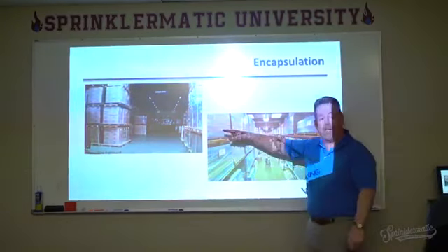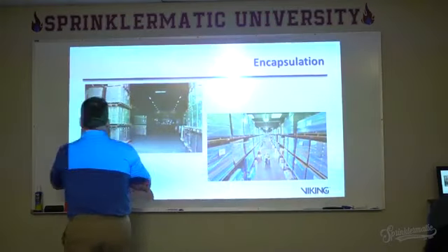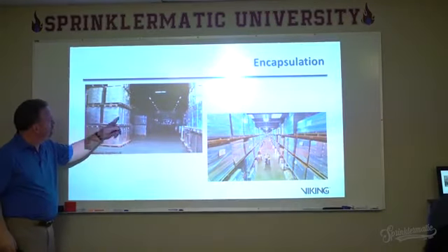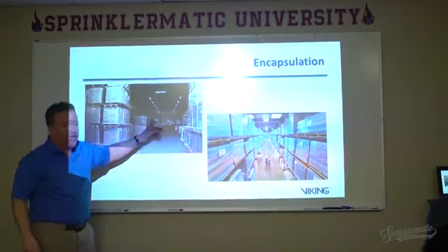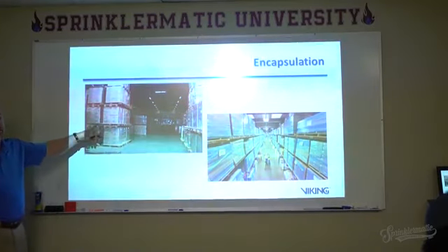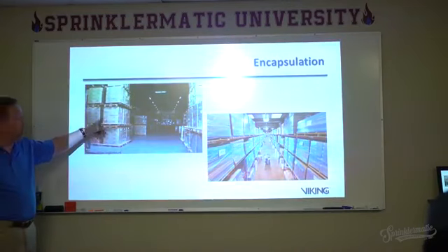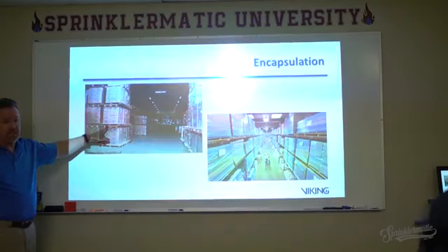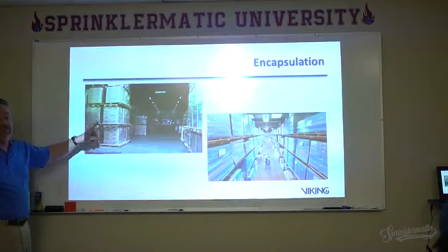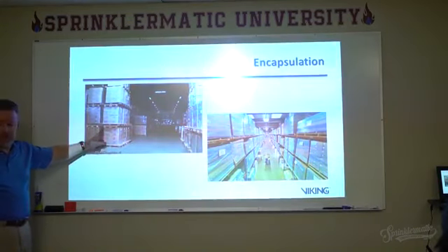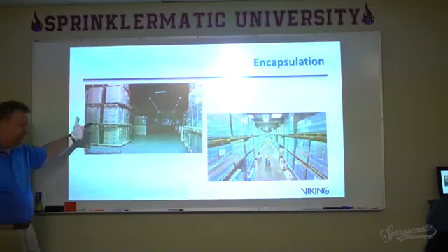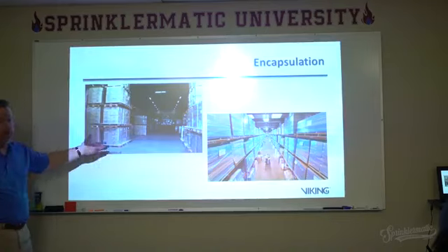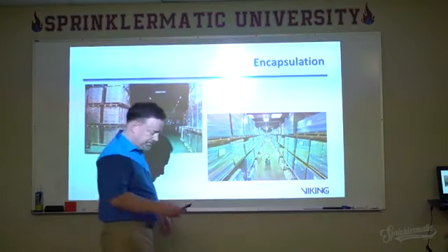If these are actually wrapped and encapsulated all around, well, you're not going to be using ESFRs or in-racks to protect this. No. But you are going to have a different flow requirement. You're going to have a different density requirement coming out of your ceiling sprinkler. So it may require an ESFR sprinkler, or it may require one of the other ones we'll talk about.